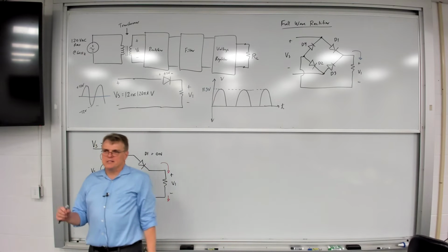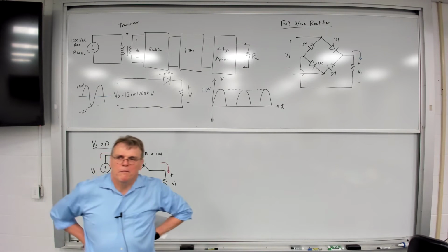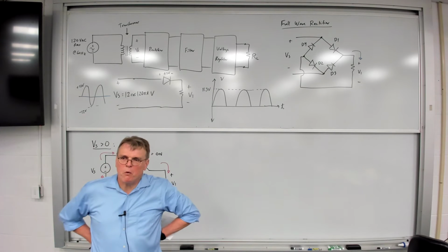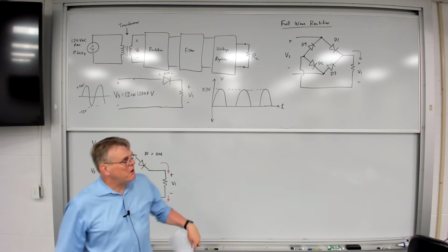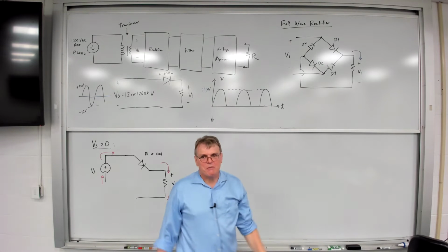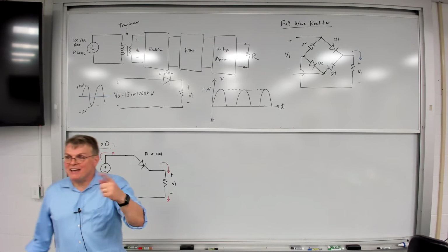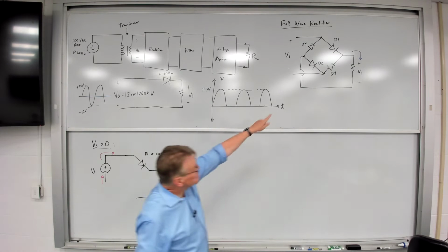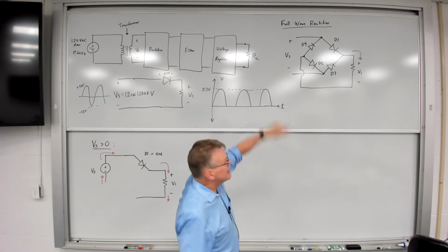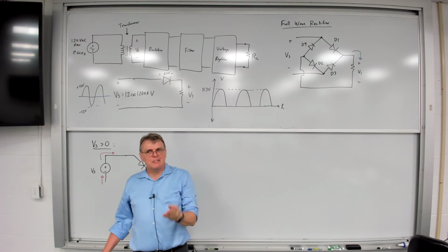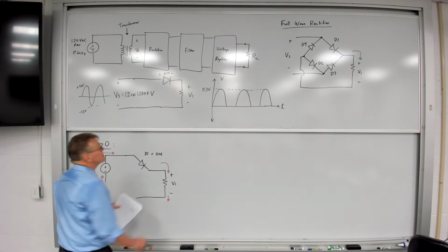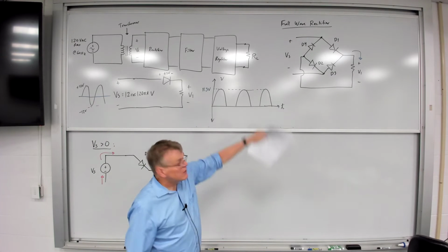Now you might look at that and say, can it flow through D4? It's at the anode, but is D4 going to be on? Well, no, because think about it. The most positive node in the circuit is the cathode of D4. The anode will be less positive because there's a voltage drop that it just traveled through for that V1, for the resistor. So D4 is reverse biased. Even though it looks like the current can go into the anode, that diode is off. And so in this case, the only place it can travel is through D2.